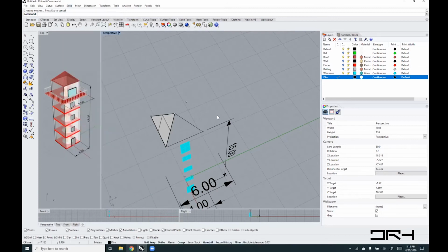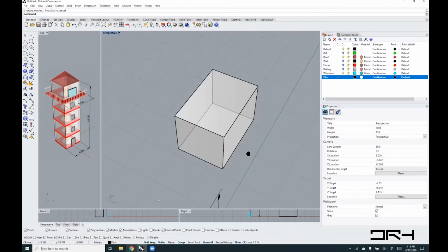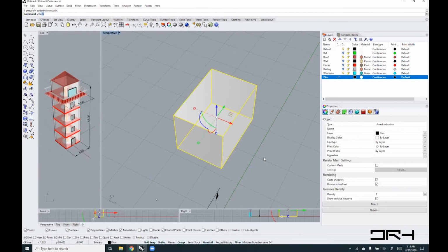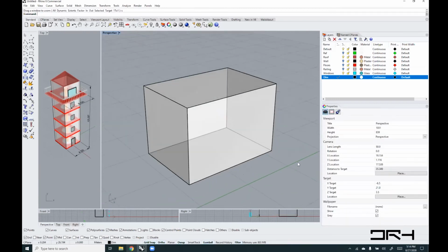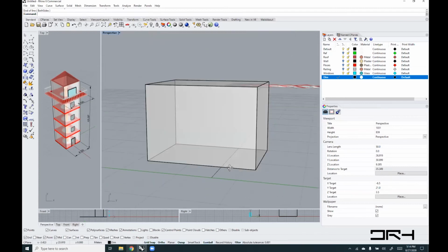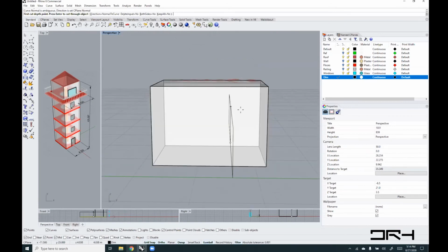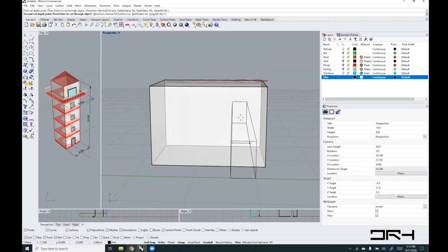One of the commands that I really like, and I've actually written to cut holes out of things, is called wire cut. So if we have a box, for example, and you have some sort of a wire, let me zoom here around my curve. If you have a line somewhere across and you want to use it like a hot wire to cut through, there is the wire cut command, which you select your wire and the objects you want to cut. And then you want to drag it in any direction you want. So drag it vertical and then there.